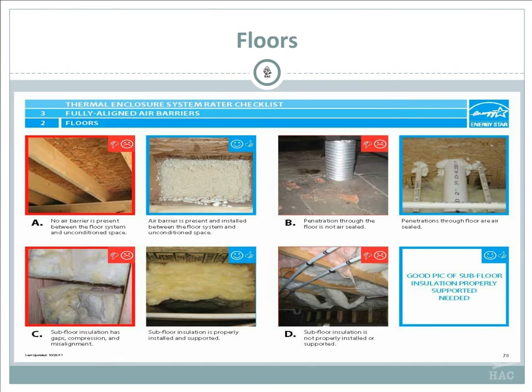One thing you want to remember when you're insulating floors is that you can't have any voids in the studs. So if your studs are 2 by 6 and the whole floor is 2 by 6, you need to put an R19 in there to fill that stud up with insulation all the way from the floor to the bottom of the stud.